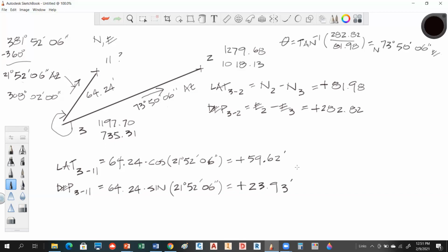Is that correct? Yes. Well, we have to assume, we don't really know that, but we do know that we measured the distances in feet. So you have to understand that your coordinates are probably in feet. It would be crazy to be working with meters on your coordinates and then measuring things out in feet. That would be such a place for error that would not fly. So those are definitely feet in this case. So what do we do with those?